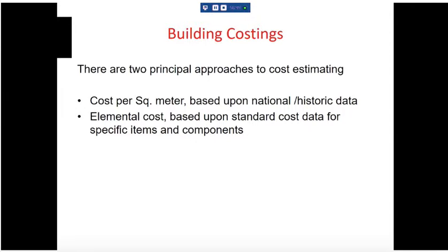Cost per square metre. Now, there's all sorts of little rule books that tell you what rate is right for a shed, and what rate's right for a school, and what rate's right for a library, and you can kind of pull them off. The thing to watch, however, is that we've just done that for this house, and it's going to be £2 million. But what I forgot to tell you was it's right on the edge of a cliff, it's got a 2-mile road going to it, and we've got to put pile foundations. So the road's going to cost you 50 grand, the pile foundations are going to cost you 20 grand, and the fence to stop people falling off the cliff is 5,000. So all of that wasn't in the cost per square metre. Those are extra costs, and we need to bear them in mind.